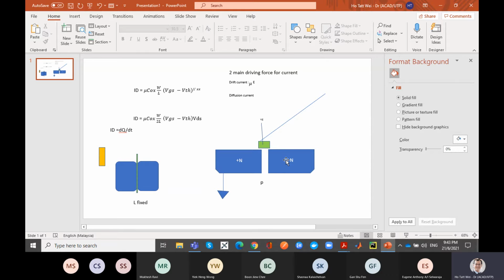That's why we need to take care of what we call the subthreshold behavior. Because that subthreshold behavior comes from the fact that there is a parasitic BJT here. Although I'm not exactly having a terminal on the base, what I essentially have is some kind of capacitive bias circuit.